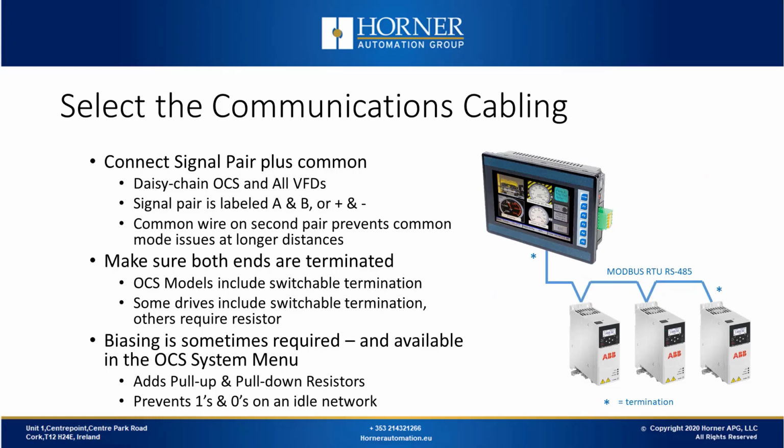The next step is selecting cabling. This is all about the cabling details for Modbus RTU over RS485, which is the most common electrical interface between a PLC or OCS and VFD. From an Ethernet standpoint, there's Ethernet type communications cabling, where you wire from each component back to a switch. CANopen is typically a daisy chain using special CAN cabling.